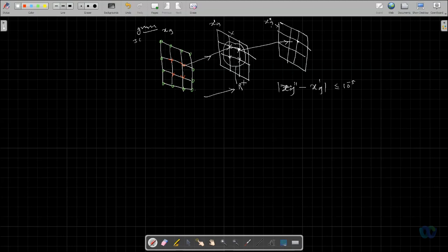So you will say that here everywhere Rg prime is also 0, sir. So I should stop here. No, Rg prime and Rg will not be 0. It is possible. We want such a case where xg prime and xg double prime and xg, I mean the present iteration and previous iteration values, should be 0. We have to proceed forward in iteration. So it is like a transient approach. It is like you are moving in time and going towards steady state. That is the meaning of false transient.